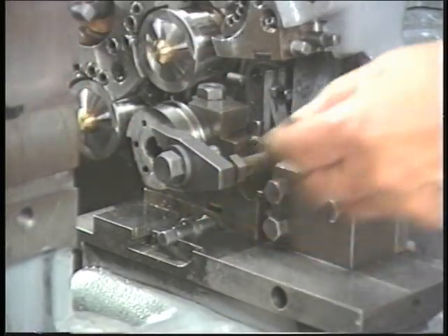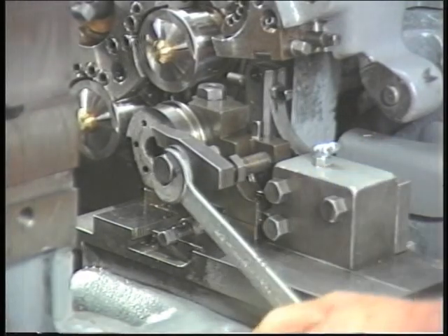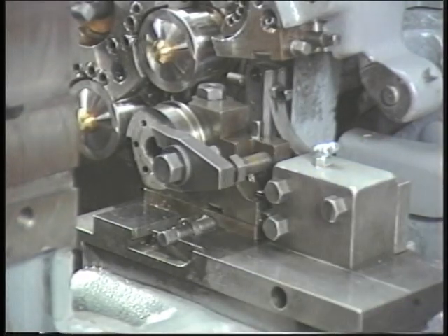Screw the tool clamp bolt so that the tool clamp presses against the jack bolt and the side of the tool. Snug up the tool clamp bolt against the tool clamp for final adjustment. Do not tighten. Once the tool has been inserted and snugged up, bring it to center as follows.